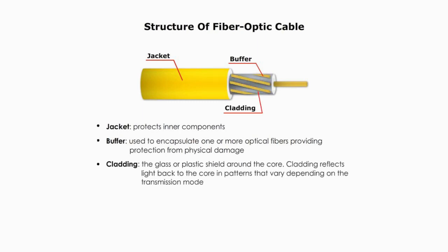The layer around the fiber core is cladding. Cladding is made of glass or plastic. The cladding layer serves two purposes. 1. It protects the core. 2. The cladding reflects the signal down the fiber. In other words, light travels through the core by constantly bouncing from the cladding. Because the cladding does not absorb any light, like a mirror, the light can travel great distances. Besides, the light bouncing or reflection from the cladding allows fiber to bend around corners without affecting the transmission signal.